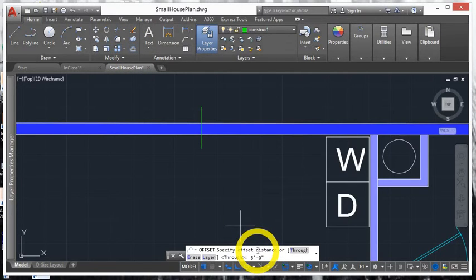When we're using an architectural template and I'm entering distances, I need the single quote mark to inform AutoCAD that I've done entering numbers that are associated with feet. And I need the dash to let it know that the next number that comes along is going to be inches. And finally, I have to conclude with that inch mark. So I have 3 foot mark dash 0 inch mark. I'm going to press enter.